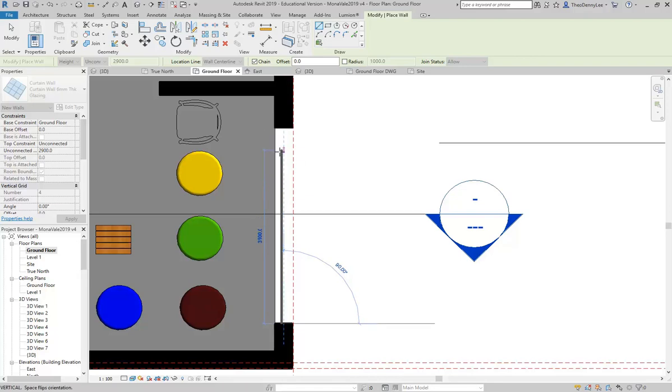And now if you forget these, you can always check. Most of the time it tells you, down on the status bar, you can see there, as I move the cursor, it's changing a little bit. So it's a bit hard to read sometimes, but it will always tell you. So there you can see it says vertical and whatever the wall type is, but at the end it says the option I'm looking for, which is space flips orientation. Now as I'm moving the cursor, you can see that text in the bottom left corner, if you're wondering where I'm looking, it's this corner here. Well, it does change a little bit, but it should generally always say, again, space flips orientation. It's just that sometimes it tells you some other things as well.